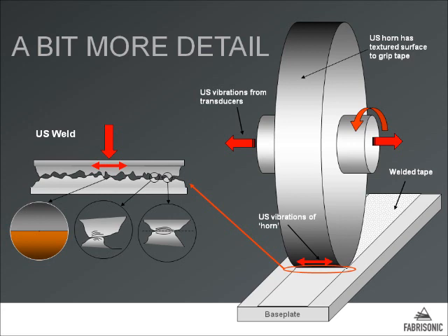In the X and Y direction, we can typically get wrought material properties of the incoming foil. However, in the Z direction, we typically take a knockdown of 5 to 10%. So we lose 5 to 10% of the normal material properties in the Z direction because of this oxide layer.